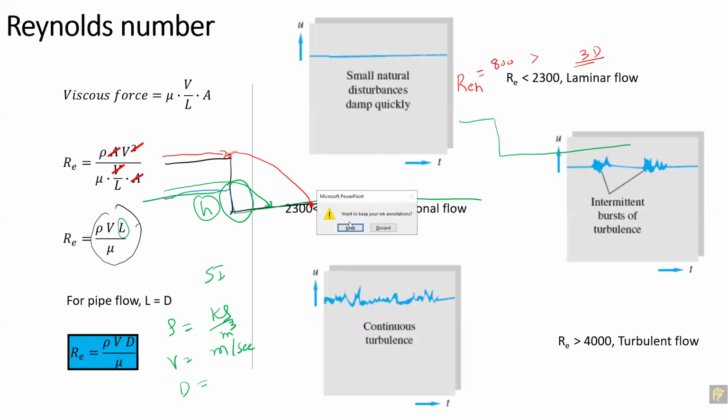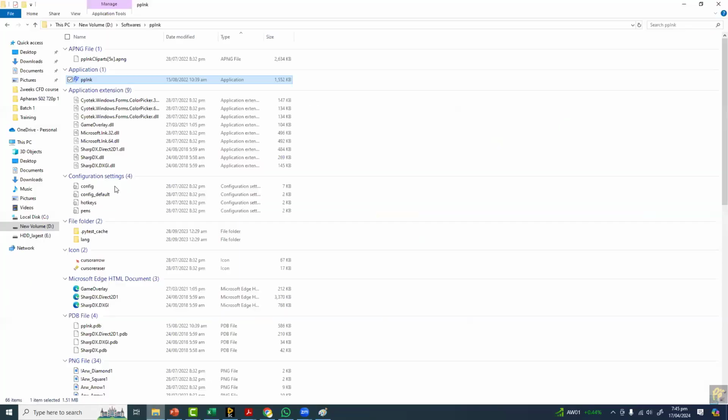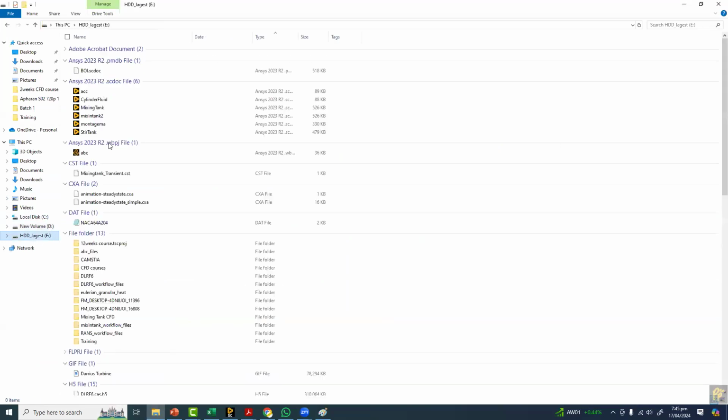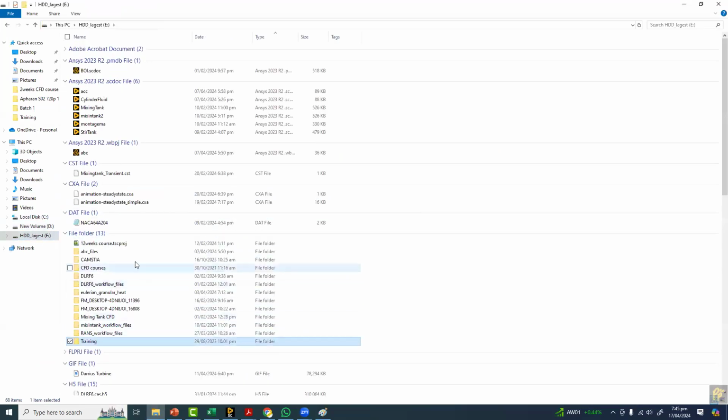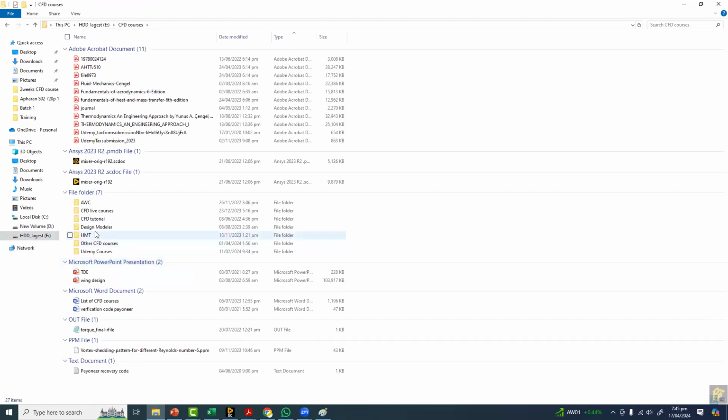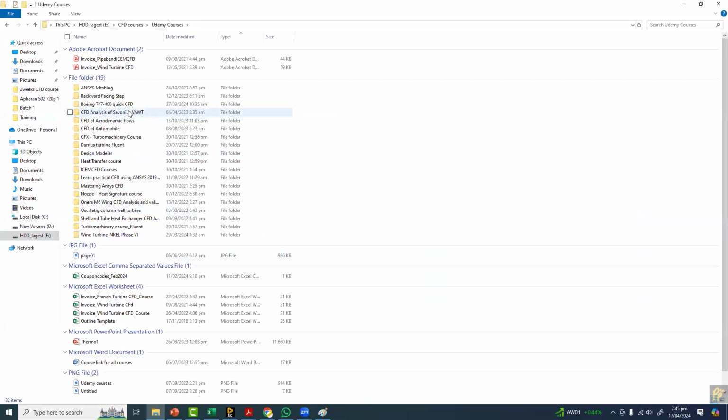Maybe this will clear your idea. I have one simulation with me that can show you this. At one time, I designed a wind tunnel for somebody. How can we test the wind tunnel? What I did is put a circular cylinder inside. We know that for that particular circular cylinder, what the drag coefficient and lift coefficient should be. So if you put that cylinder into the numerical wind tunnel, like in CFD, the results should match the actual wind tunnel testing.